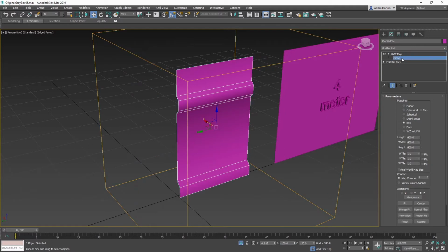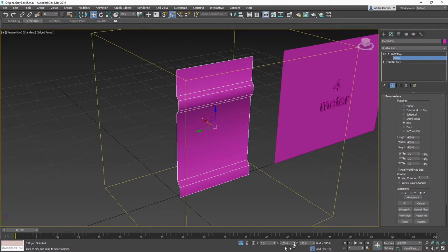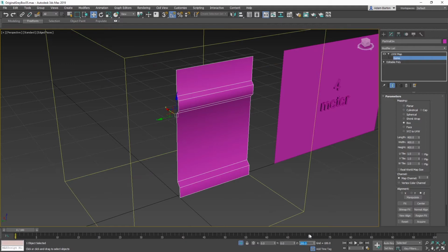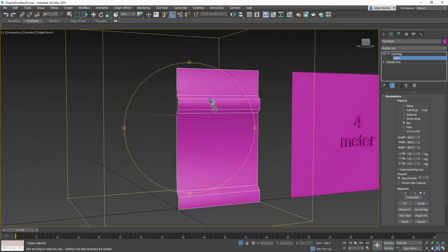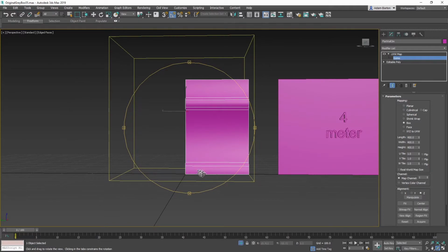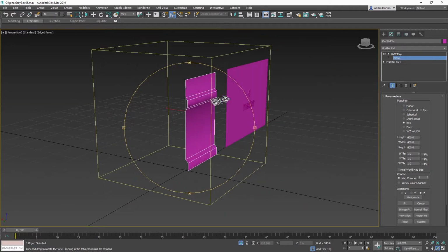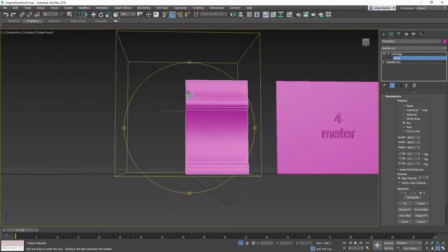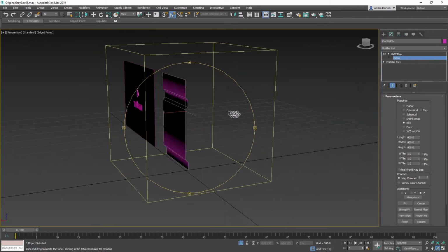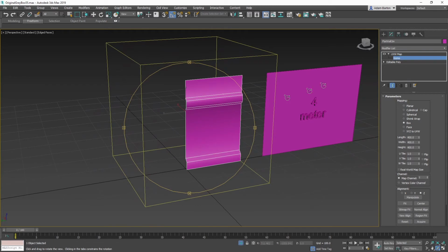And I'm also going to make sure that the gizmo is on the origin XY and 200 in the Z. And what this does is it makes sure that my UV coordinates start at the floor and go up, whereas everything else is in the middle. So in other words, we have 6 planar projections, one from each side of the cube.